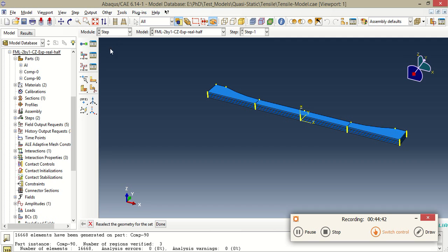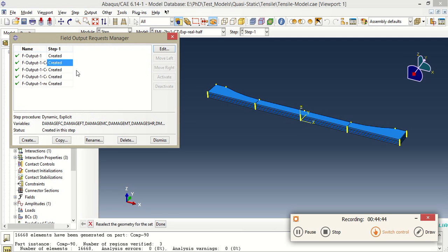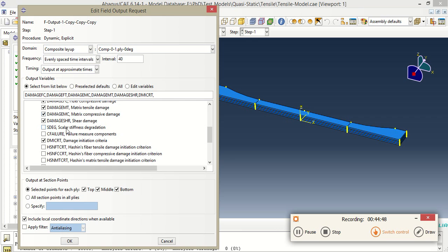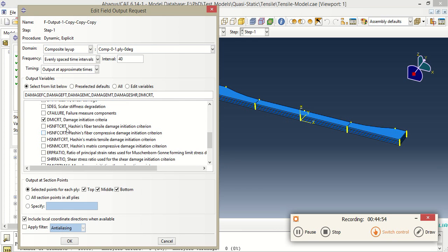Just to check it, I need to figure out these damage initiation criteria that I have chosen: Hashin failure criteria, fiber compression, matrix compression, all these 4 criteria are called through this single variable, damage initiation criteria. What are these criteria actually? Damage initiation criteria, okay, I'll tell you by drawing a simple figure.